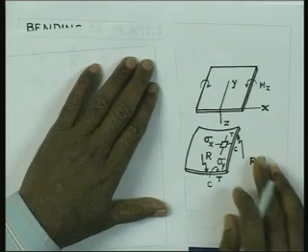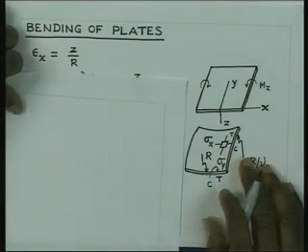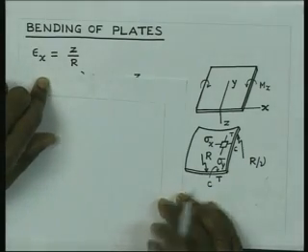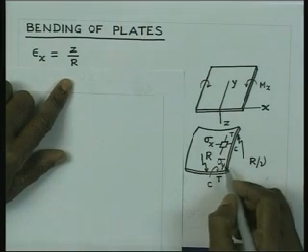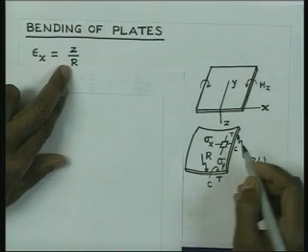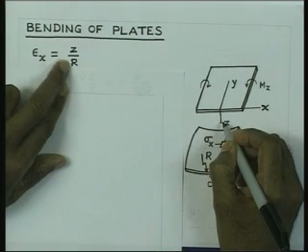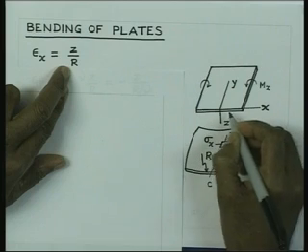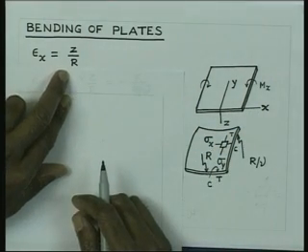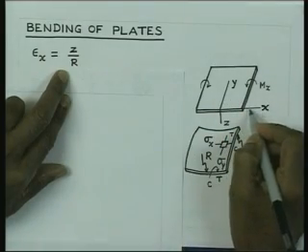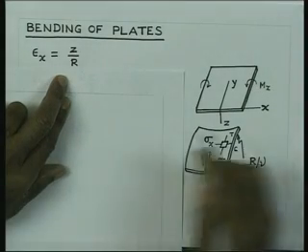And we can find out this curvature very easily if you consider that the bending is producing a strain, let us say epsilon x. So, because of this I have the bending strain which is z by R. So, for positive value of z we are going to have positive strain, and we consider that this x axis is right at the center of the plate, or the xy plane coincides with the center of the plate, and then we have this as the distribution of the strain.